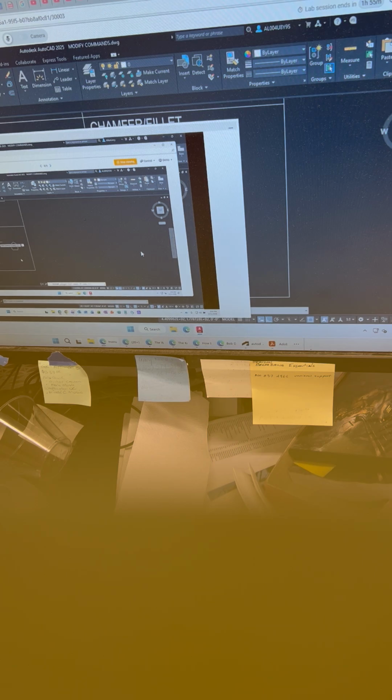All right. See how it says 5 sides? You don't have to enter that in again. Just hit enter. All right. Now, when it says specify the center of the polygon, here's a little thing I want you to do. I want you to hold down your shift key and right click. Now, let go of your shift key. I want you to select from this list geometric center.